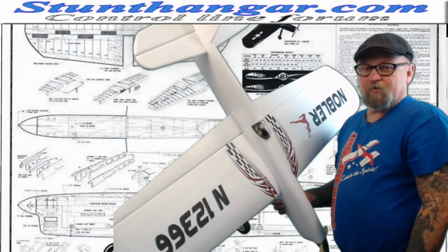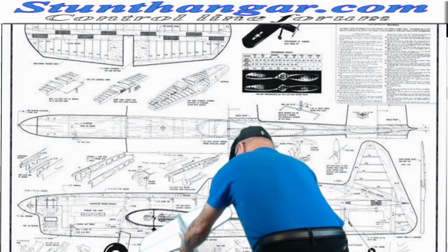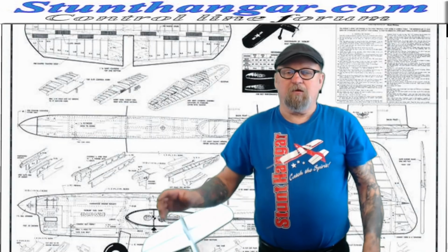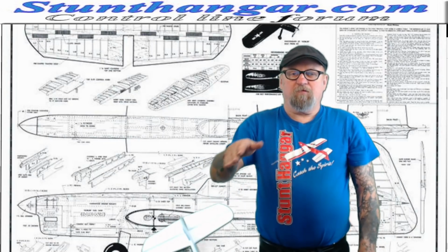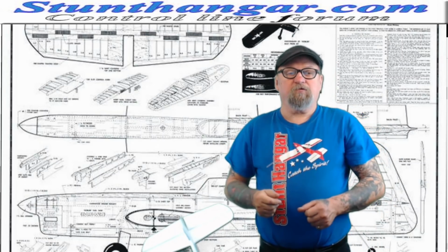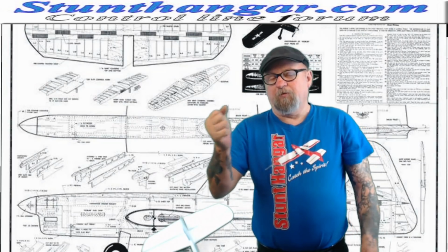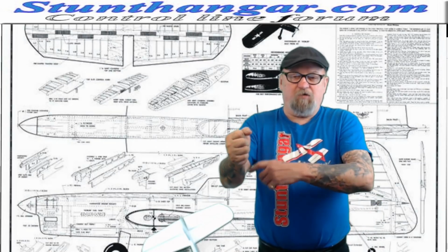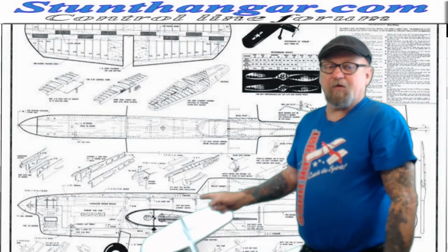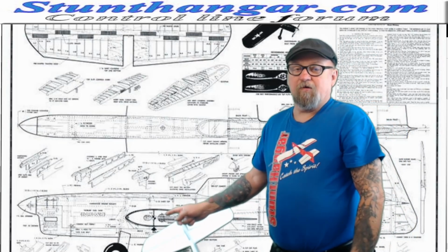Now let's talk about what lengthening the nose does for you. It sets up a thing called clock time. The longer you make the nose, the more time it takes to go around the corner, and the more nose heavy the airplane is going to feel. You have a solid piece of steel, in this case aluminum and steel, out there on the nose, a foot away, actually more than that, from the center of gravity, because the center of gravity is measured from this part of the wing right there.